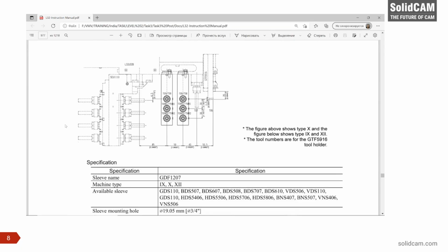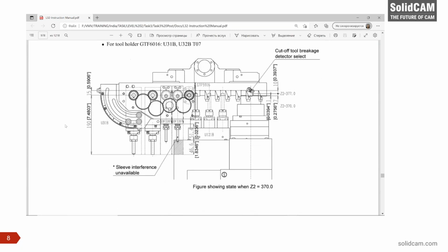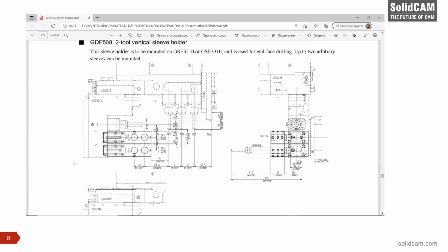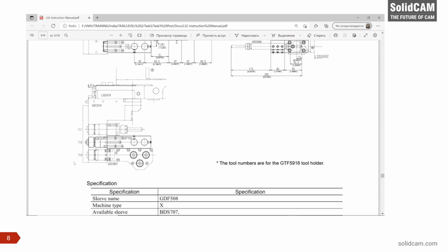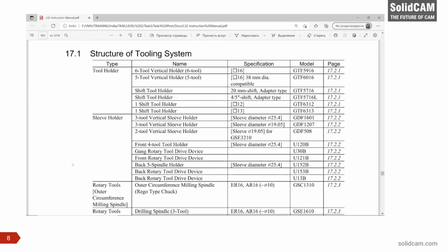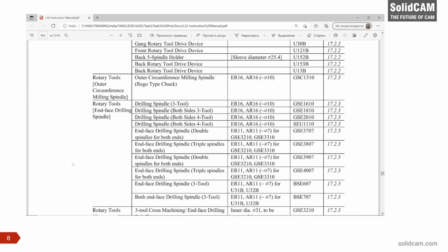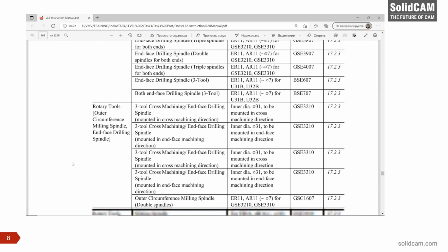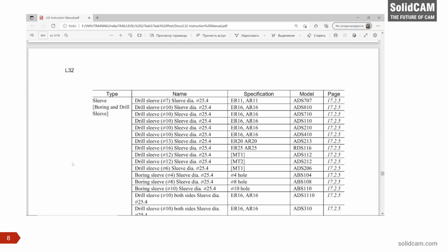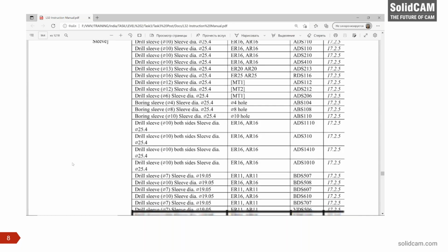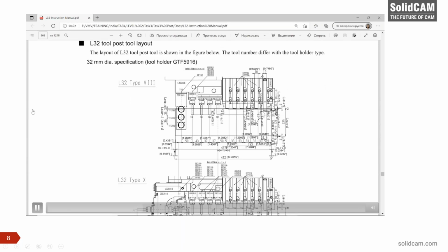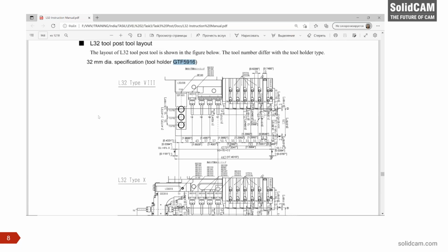And also, together with different attachments, we will have recommendations about tool offsets. Tool offsets will also differ, and I mean the tool offsets which will be output to the G code. There will be different commands. Also, there will be some recommendations about the out-of-holder length of the tool, which is allowed on this machine. So it is quite a complex process, complex and important. We need to consider it every time we deal with these machines.